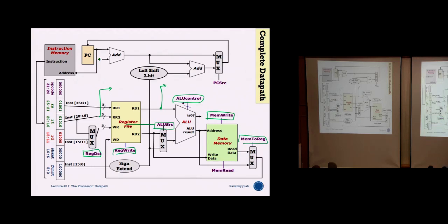So register 8 will come here, right? Yes. Then register 7, register 8 is supposed to be removed. So you come here, and you specify here. And that will come here. It will come in two places, but this will not be used. You come out here also, but this ALU source will not use this data, it will use this data. Why not just put a multiplexer in the middle, then they will decide where to go, without even going to the R2?